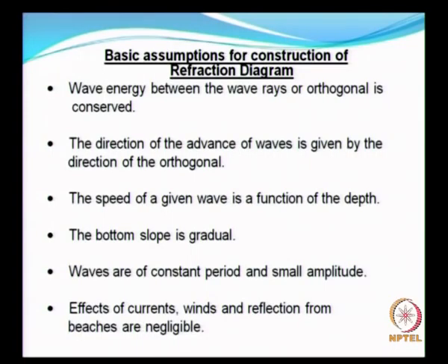While you construct the basic refraction diagram, there are some basic assumptions, some of which I have already told. The first one is already mentioned. The second one is that the direction of advance of the wave is given by the direction of the orthogonal, because that is the wave ray. The speed of a given wave is a function of water depth. We assume that the bottom slope is gradual.